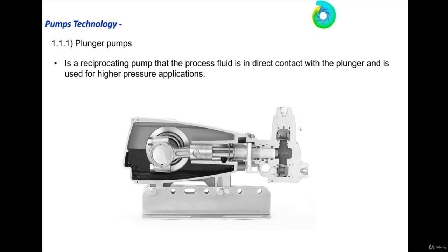In the plunger pump, as we see, there is usually a suction valve and a discharge valve. These suction and discharge valves operate against spring force, acting on the spring due to the pressure difference in the suction and also in the discharge. So there are valves in the suction and the discharge.